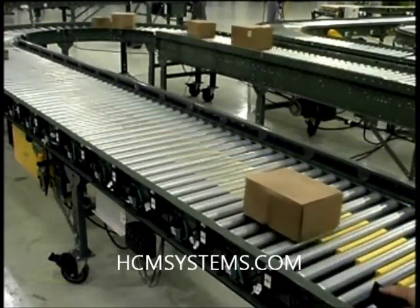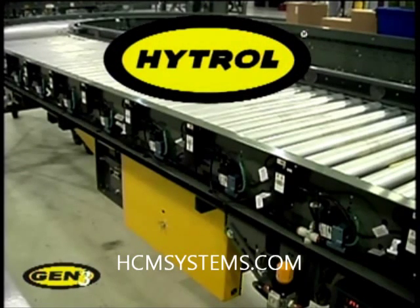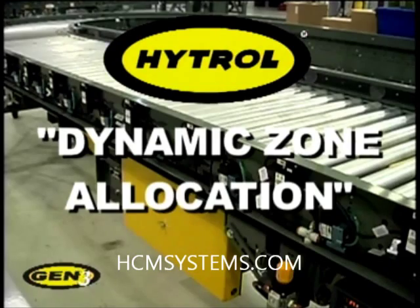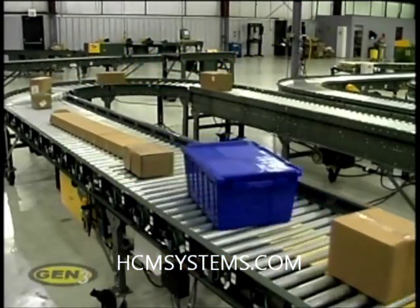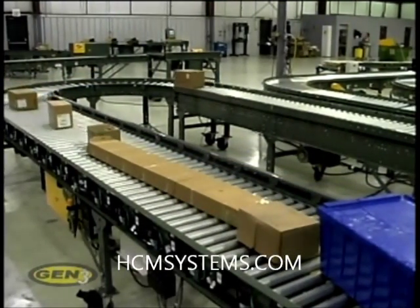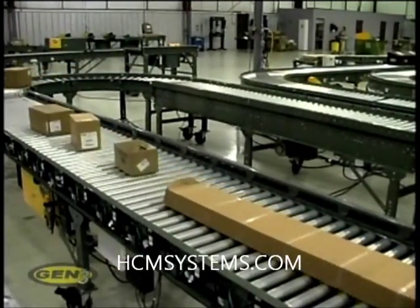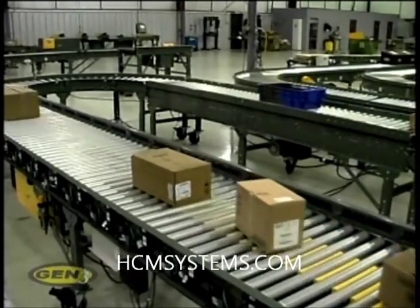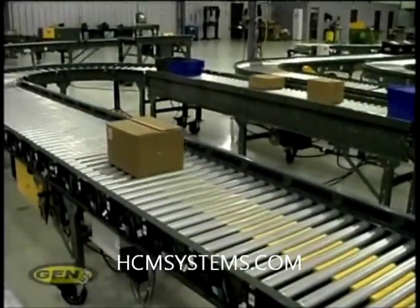The other way the EZLogic assigns zones to cartons when in singulation mode is by using Hytrol's dynamic zone allocation technology. When the zone operating mode is set to dynamic zone length, EZLogic uses a process known as dynamic zone allocation to adjust the zone length to fit the carton being conveyed. The mechanical zone length becomes the base zone length. Each carton is assigned enough base zones to accommodate its length.